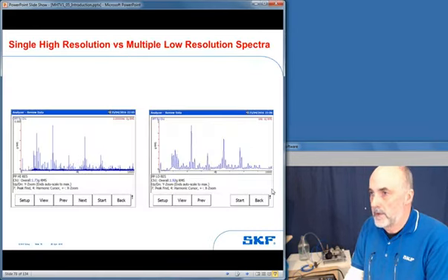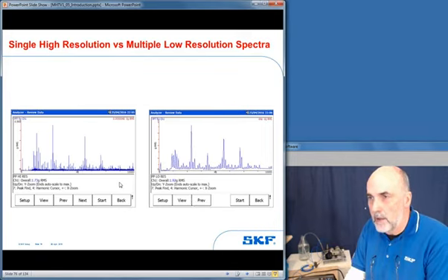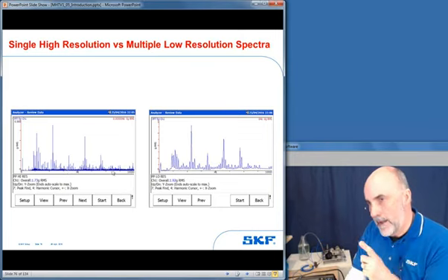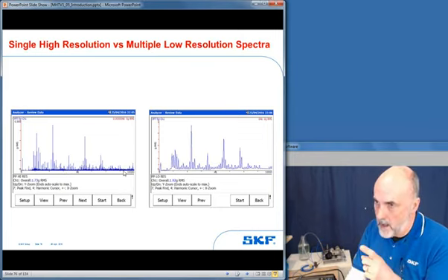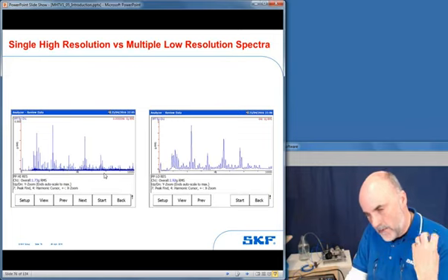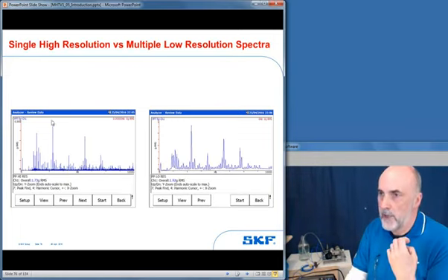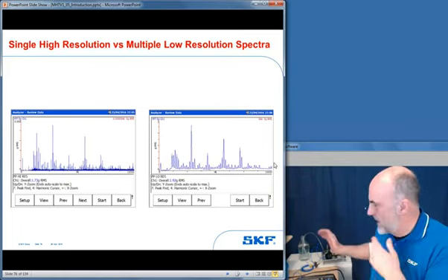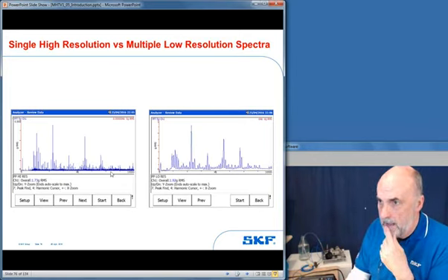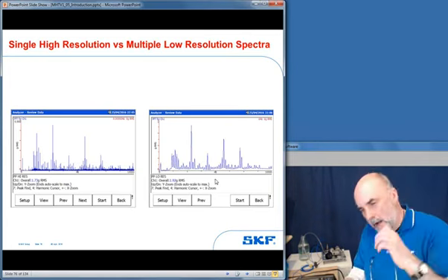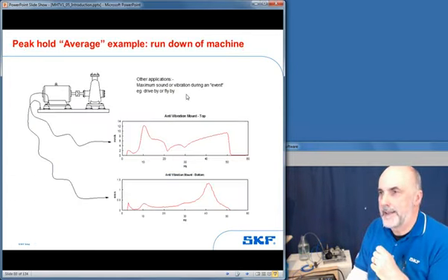So there we go. Just for fun, I've taken a couple of spectra there, one with low resolution and one with high resolution, so you can see the carpet. Just one important point about this carpet, the random part of the signal that some people often refer to. I've got two spectra there that I've recorded from this cavitating pump, and pictorially the carpet looks lower for the higher resolution spectrum. And you can play games with the peak to carpet. I'm going to mention that a little bit later.